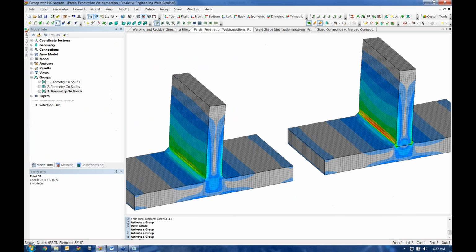I've got some simple examples here. We rarely do full solid models of the weld. Again, I can generate stresses in here, but it's not totally going to be accurate because I can't always capture all the details of the weld. Also, the residual stresses from the welding and any sort of warping probably aren't going to be incorporated into my model. But what I wanted to show with this was the big picture: full penetration versus fillet welding.